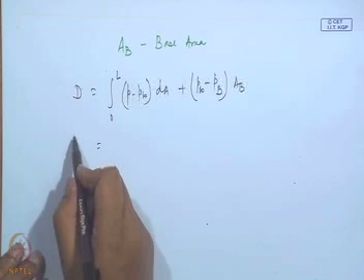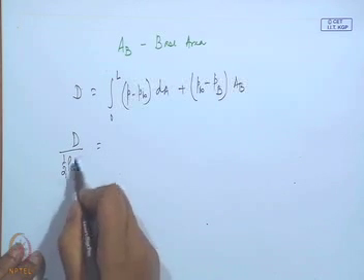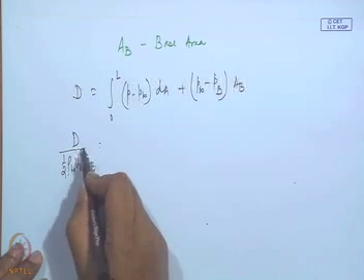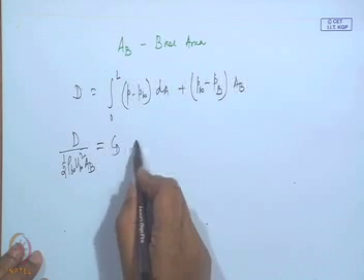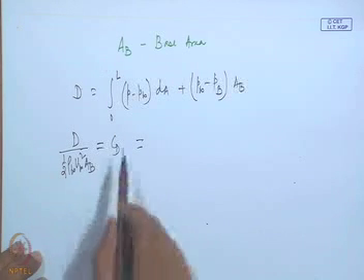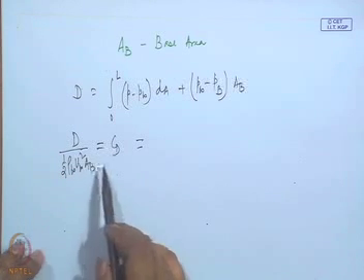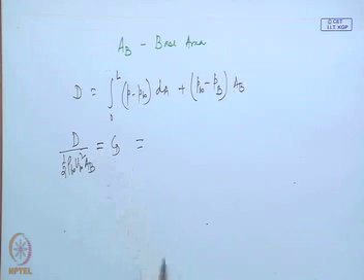Then, if we divide this by ... that is, we are defining a drag coefficient based on the base area, not on the planform area as usually done in aerodynamics of wings or in incompressible flow aerodynamics, where the drag is always based on planform area.